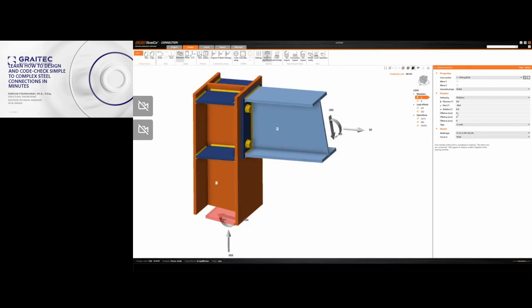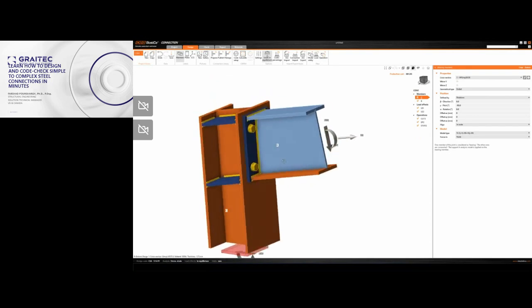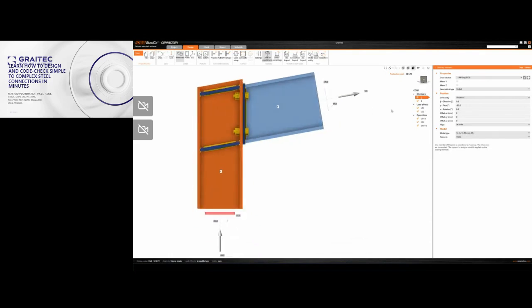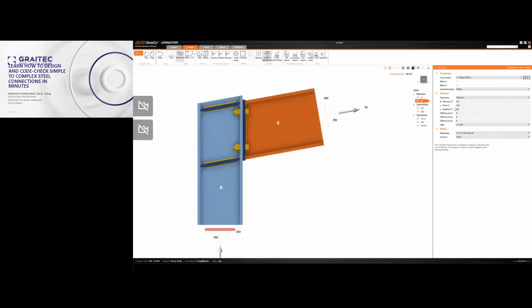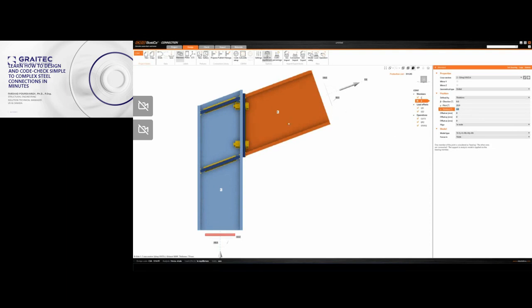We also have other tools here for replacing the elements. For example, if I go to side view, and let's go to beam, member B, you see that I have 10 degrees of pitch here. If you want to change it, you can just click and let's change it to 20 degrees, and there you go. So you can change the orientation in 3 directions.